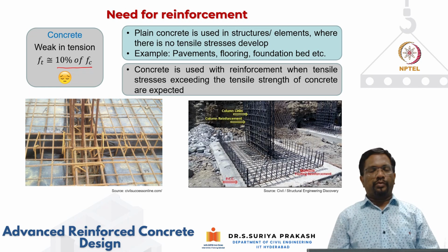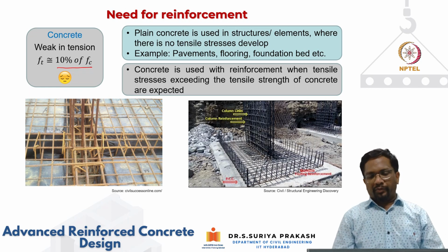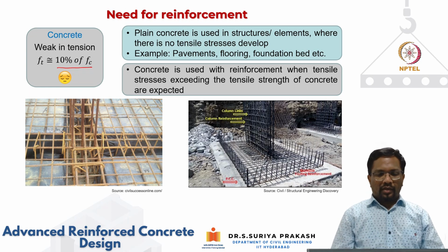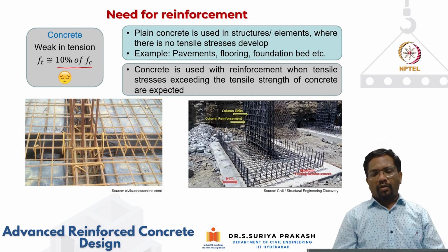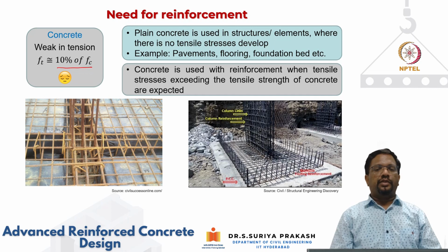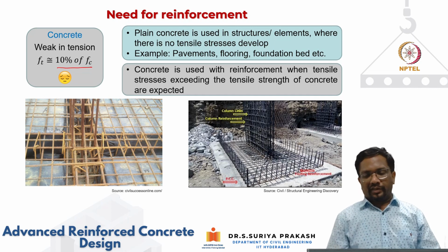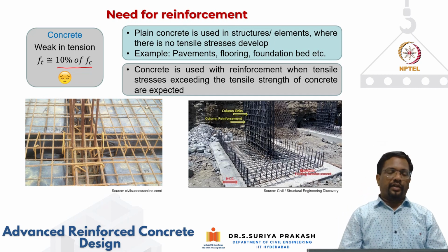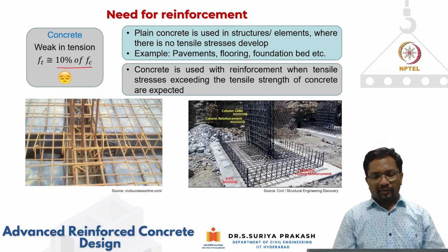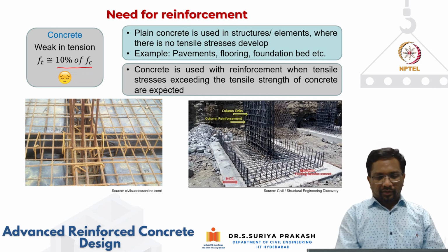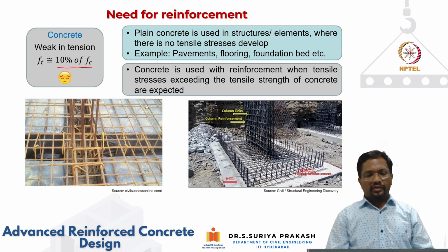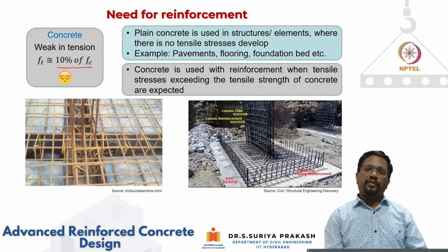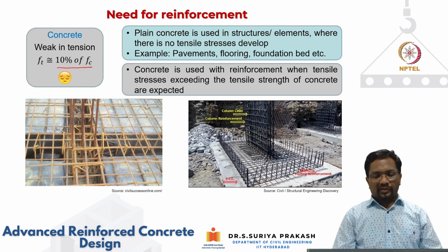There also, it is good practice to provide some minimum reinforcement. But in most applications, concrete is used with reinforcement, mostly steel, to tackle the tensile stresses that are coming from applied loads. You can see several examples shown in the figure where we are using reinforcement to tackle different types of tensile stresses that develop.